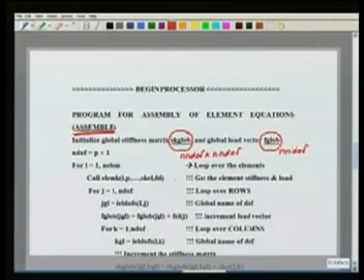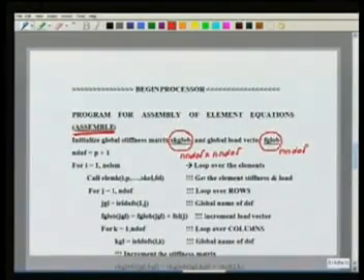You see what had happened in a previous program, as we kept on adding the degrees of freedom, our counter for the total number of degrees of freedom kept on getting incremented, and at the end of the program we had the total number of degrees of freedom in the domain. So once we have all this, we have the n doff and so on. So we can first initialize the global stiffness and the load vector. Then we say, in the element, how many degrees of freedom are going to be active? Given the order of approximation p, it is going to be p plus 1. So we name another variable called n doff, which is equal to p plus 1. Then we start looping over the elements.